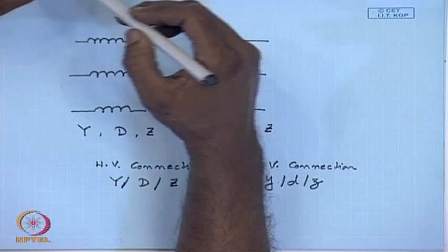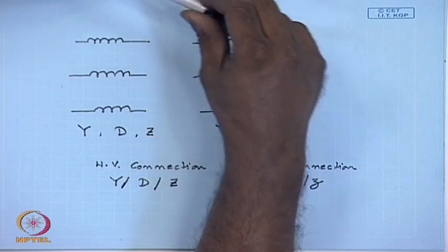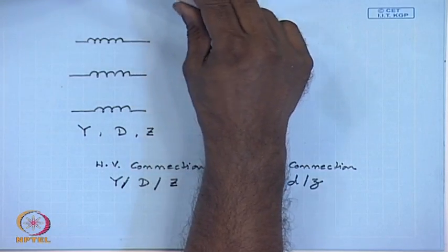However, that is not sufficient. In our last lecture, we have seen how to find out the line voltage and current as well as phase voltage and current conversion ratios of a 3-phase transformer given the winding turns ratios. So, we have seen that the voltage magnitudes on either side are different, that is the purpose of the transformer. However, a closer scrutiny will reveal that not only are the magnitudes of the high voltage and low voltage sides different, in many cases they are also not in phase.